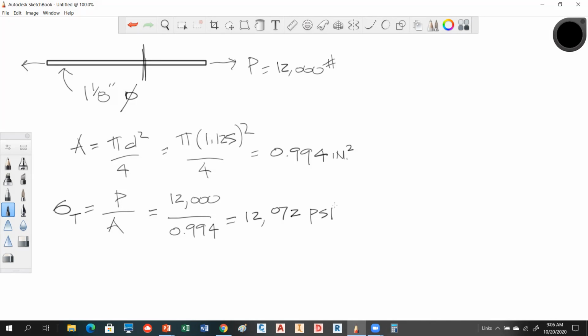So what would be the case, let's say, if this rod has an allowable stress in tension? So the allowable stress in tension is actually 20,000 pounds due to the material. So this is the allowable. So what would be the maximum force that you could put on this rod before you would fail it? Or fail, you wouldn't necessarily fail the rod. In other words, you wouldn't necessarily break or rupture the rod, but our design would fail. So we want to see what's the maximum, and we want to see if this has already exceeded the maximum or not. So here's how we handle this problem.